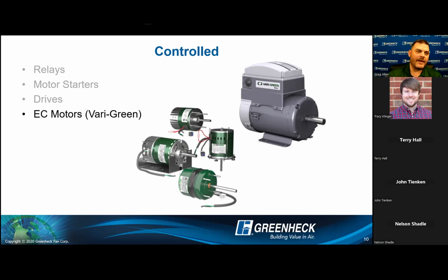And that's because every EC motor that's out there actually has a drive built into it. Otherwise, it'd just be a permanent magnet motor if you had an external drive, I suppose. You could look at it that way. So EC motors have drives. That drive gives it the ability to accept either a potentiometer or a 0 to 10 volt signal for speed reference, soft start, as well as all your motor protections, right? Because it's a drive, it has motor protections built into it. So these are common controlled items within our industry.